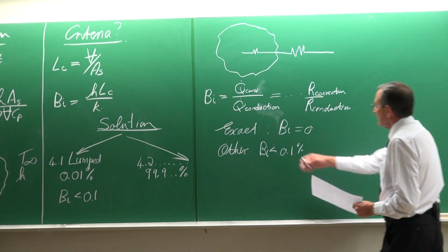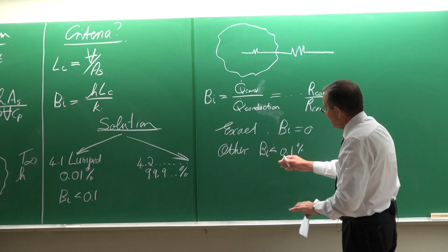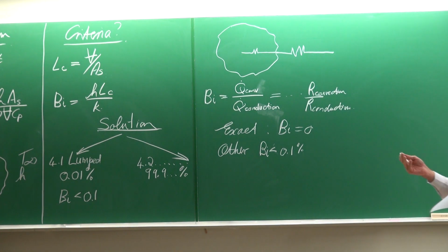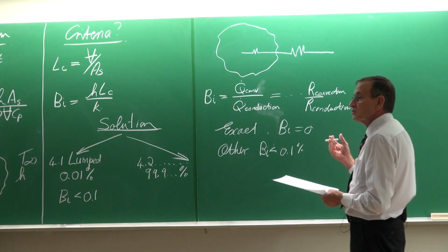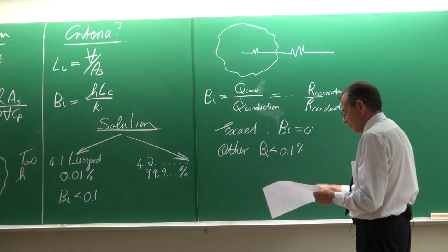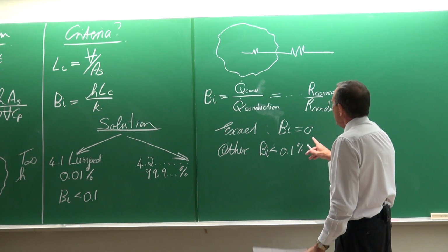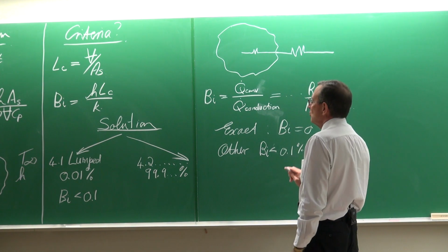Now, except for the fact that it is very simple to calculate the Biot number, and based on whether the value is smaller or larger than 0.1, just continue with all the calculations, it is also just as important that we understand where this comes from, and why we can only use it if the Biot number is so small.